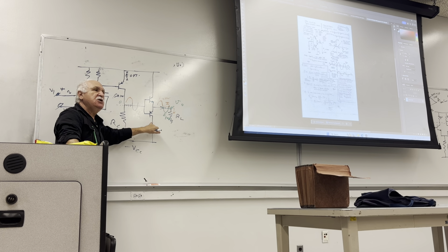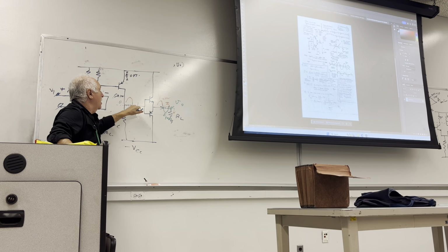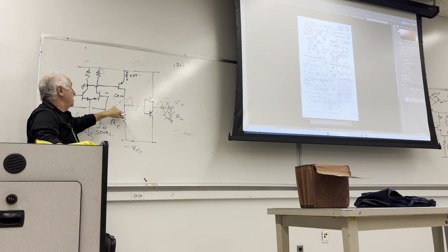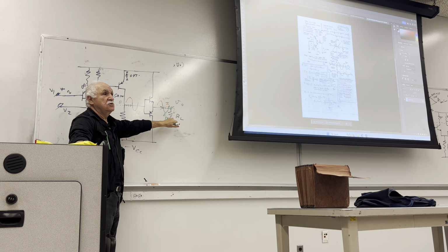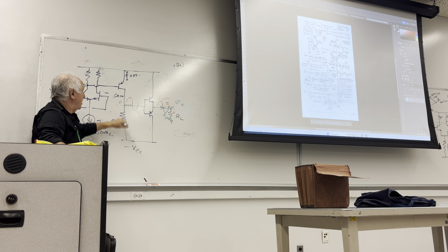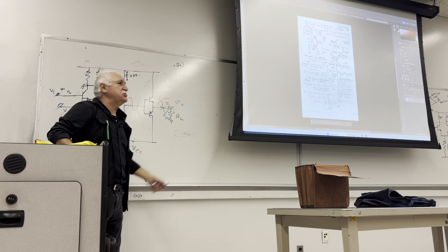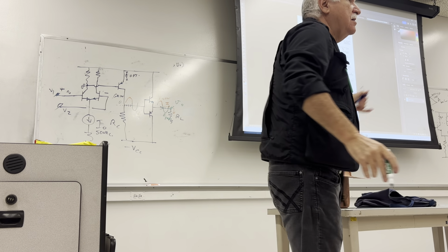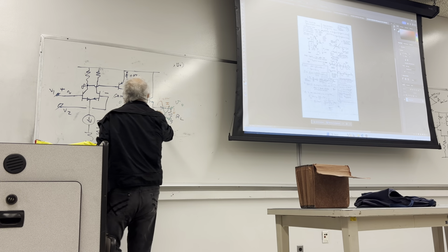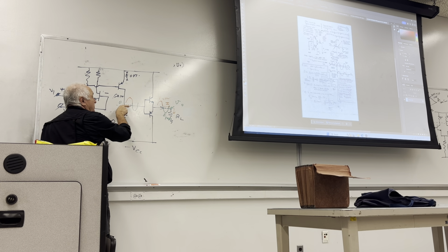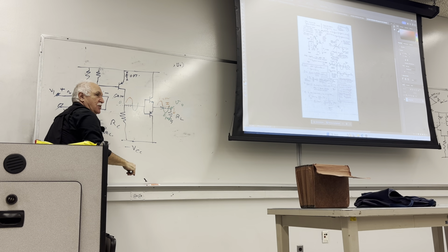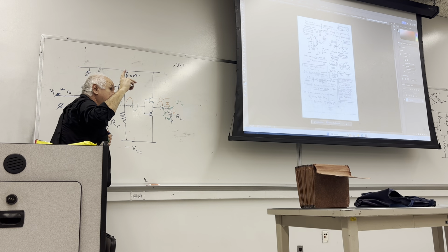This is a power stage. It's capable of driving a lot of current into the load because it's going out of the emitter. Unlike this guy, this is unable to provide that current to the load. Why? Because the current in this stage is typically a biasing current. You know, like milliamps, 5, 10 milliamp, that's it. But in here, you have a booster that when the current goes out, it will be amplified by the beta of each individual transistor. Why do we need two?